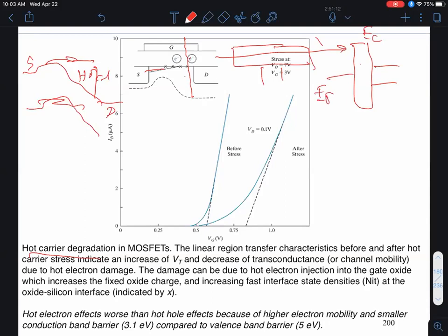That's my EFM, the work function, the Fermi level in the metal. That's EC, EV in the oxide, EC, EV in the silicon. Are you guys with me? So I'm plotting the band diagram as a function of depth, but I'm flipping the diagram by 90 degrees. So this is the high band gap in the oxide. That's a lower band gap in the silicon, right?